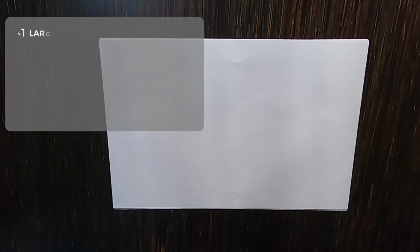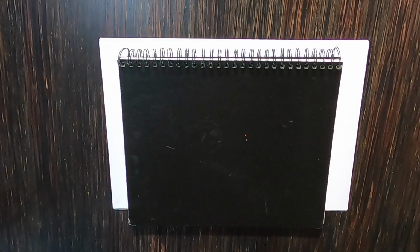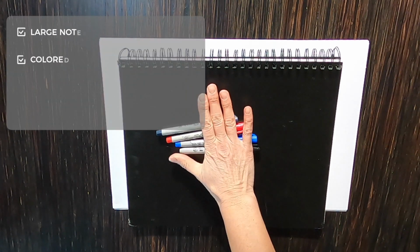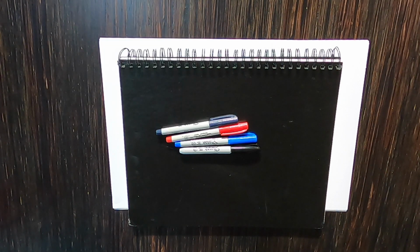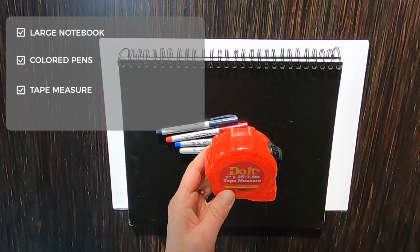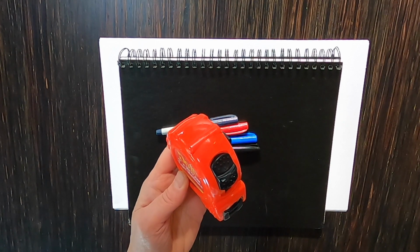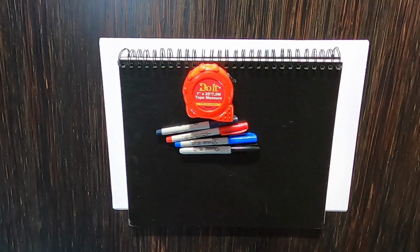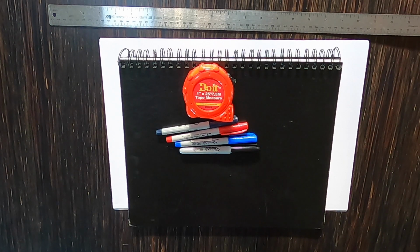Okay, the tools you'll need are a large notebook. Larger the better. I like to draw one room per page. Some different colored pens. You'll realize why this is so important in a little bit. A tape measure. I like to use construction size, 25 feet, and then just make sure it has some sort of little locking button on there. Last, you'll need some sort of long straight edge. If you don't have a ruler like this, I've been known to use a pool cue or even a broom handle.